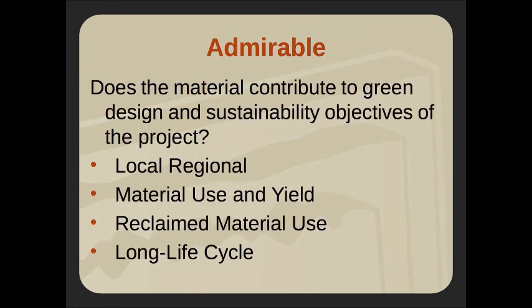Are we interested in LEED? I think most of us are, but is it a city spec where they are actually requiring that it's designed to LEED standards? And if so, are we keeping that in mind? So there's a sustainability goal for the job, and we need to make sure we're falling in line with that. If it's a local regional project, we want to make sure that we're finding material within that 500-mile radius that's going to be appropriate, not just close, but appropriate. Just because it's within the radius doesn't mean it's the right product. We want to make sure it's the appropriate product.